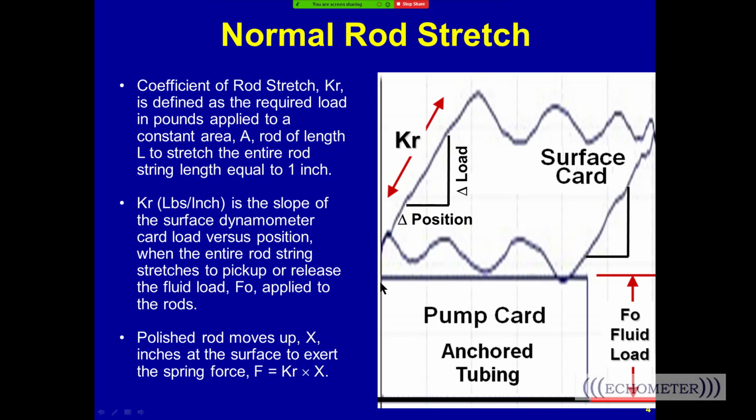The wave equation views the fluid load as applied to the bottom of the rod string, and when the rod loading increases here, we're picking up the fluid load being applied by the differential pressure acting across the pump. And that causes the rods, based on their lengths and diameters, to have a certain amount of stretch per pounds per inch.